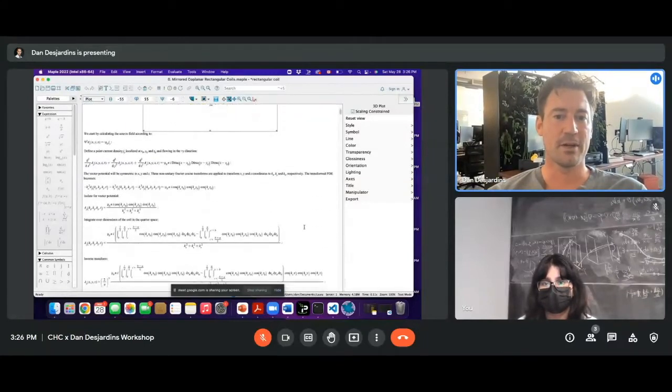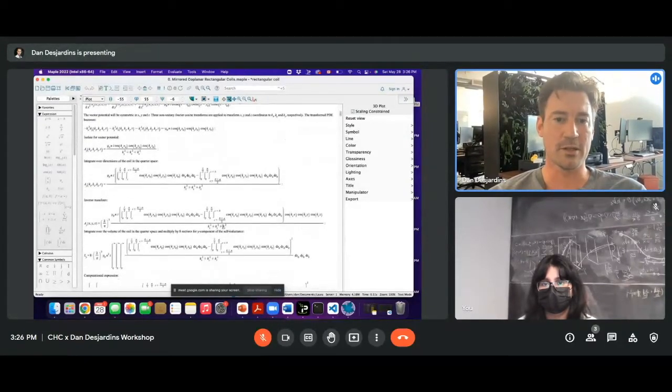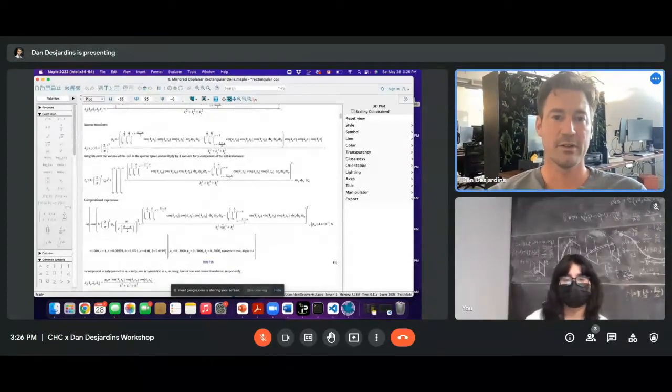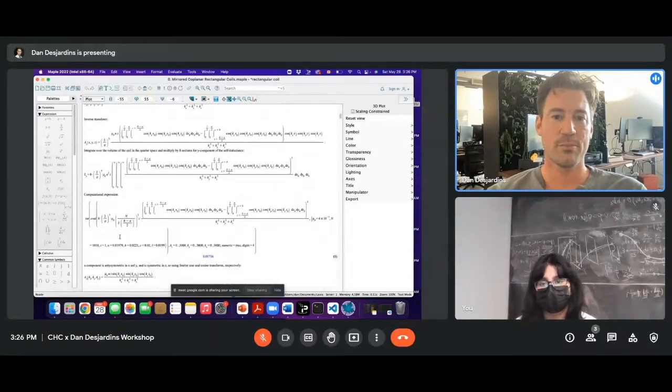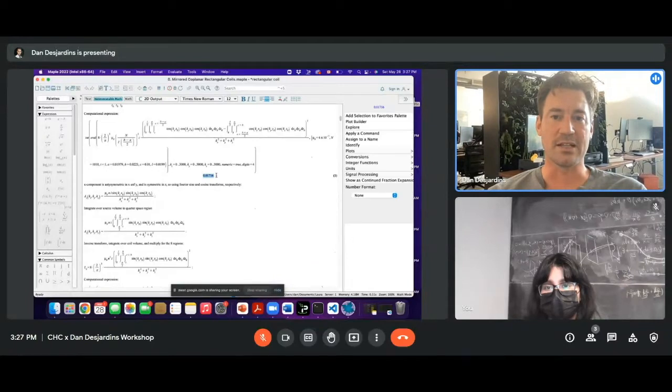But the math here, and I don't want anyone to get any nosebleeds, that's not the point. But I do want to show you the elegant complexity of it. We're doing triple integration over kz, ky, kx from 0 to infinity essentially, and somehow these things are giving answers that are exactly matching experiments. So this is telling us that the self-inductance of one of those rectangular coils is 17 millihenries, and the experimental answer was 16.95.